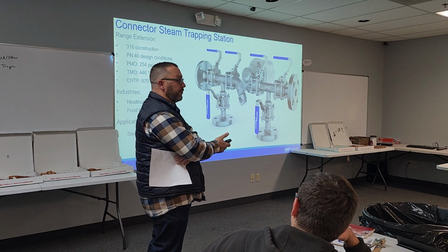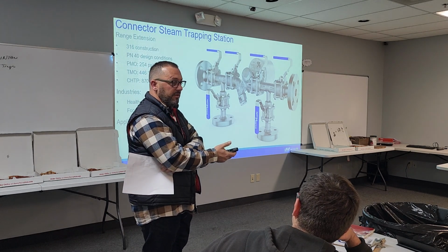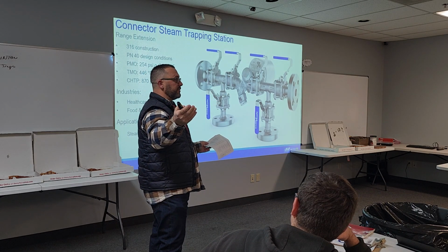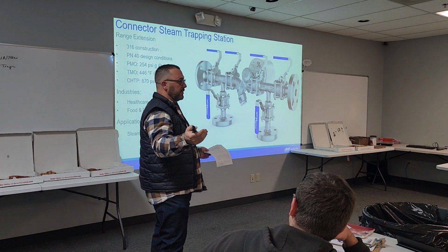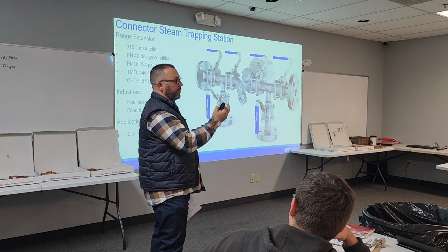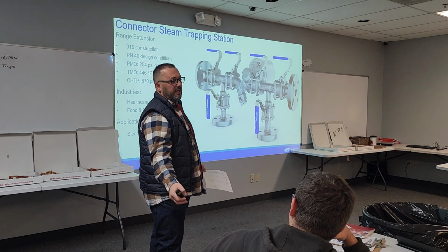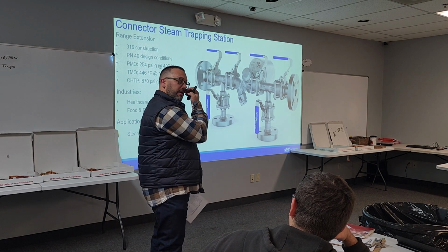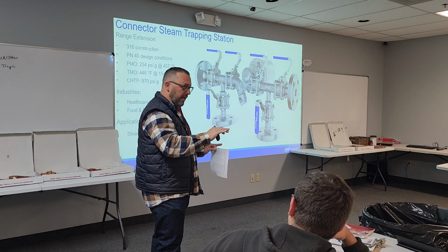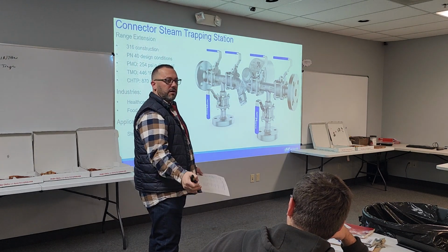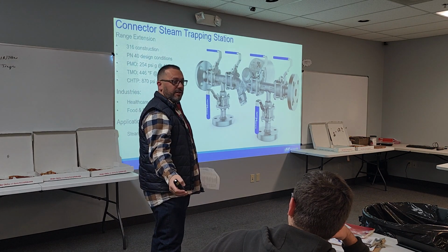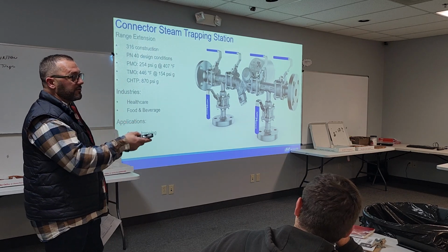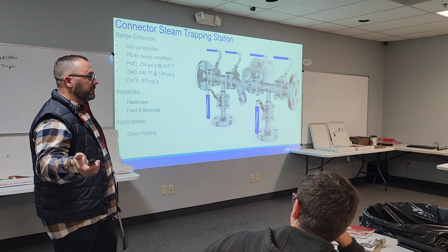I don't see many people footing the bill from a piping perspective. Blank sheet of paper, if I'm designing a steam system and somebody's trying to be tight on their finances, put Schedule 40 on the distribution and Schedule 80 on the condensate return. The condensate is worse usually. If everything's sized right, you don't have increased velocities. I'd rather see personally myself seamless on everything, 80, all across the board. But as far as to answer your question, 316 stainless L, low nickel.